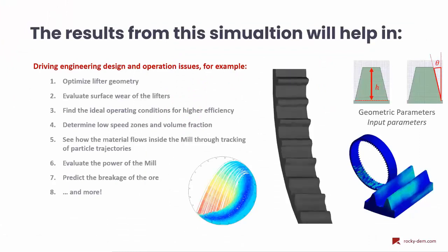So the results from the simulations can be critical for driving engineering design and plant operation issues. They will help to optimize the geometry of the lifter, find the best height and inclination, and evaluate the surface wear of the mill over time. These results will allow you to find ideal operation conditions.